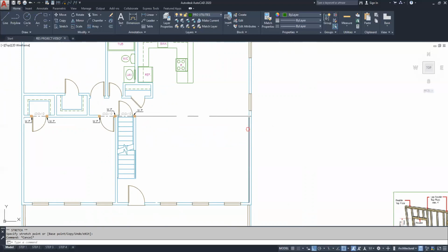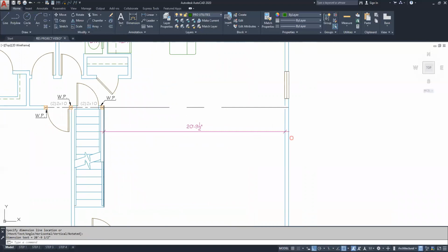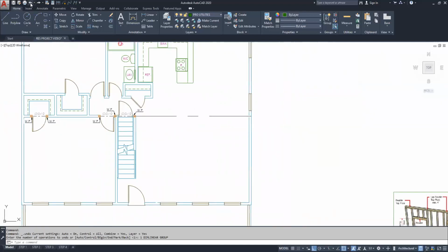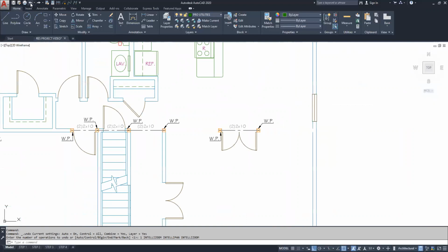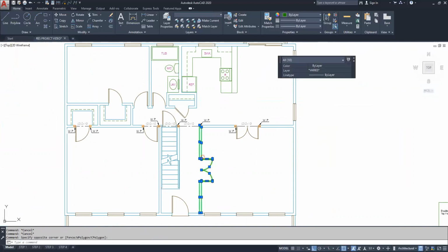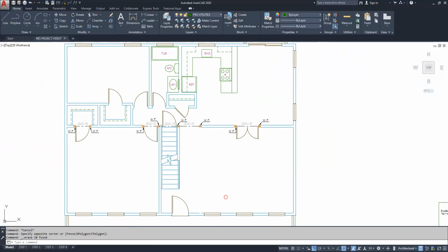When you're calculating beams, one of the biggest factors is known as the span. So how far are we spanning? From here to here is 20'9". So it's quite a distance. I'll put everything back. There you go. Okay, so that's a bearing wall. This one's not a bearing wall. If the homeowner decided to just take this down, pretty much they can almost do it themselves. It wouldn't be the end of the world. All right.